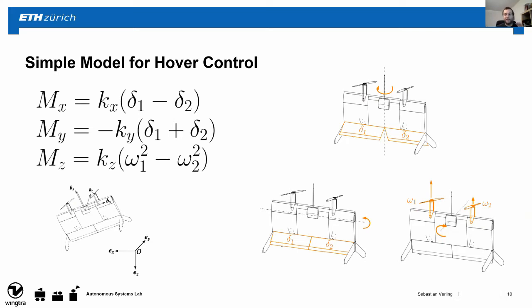Now, these are rather simplified assumptions, as for example, we didn't look into how different propeller speed and inflow speed change the efficiency of the flap and the moment generation here. But because we wanted to go simple first, and then we can still increase complexity as the project goes along and we see issues with it. The reason why this is okay is in nominal hovering conditions, it's okay to assume that the overall velocities are rather small and the propellers turn approximately always around the same RPM.